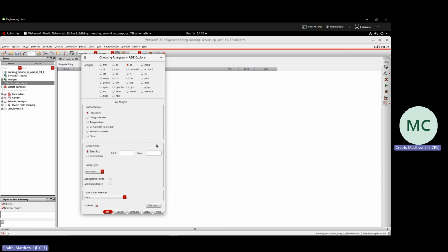So the gain bandwidth for a single pole system, which our op amp is, should be about the same as the unity gain frequency. So we expect it to be about 10 megahertz. So I'm just going to go 1 decade beyond that to 100 megahertz. So we can put 100, capital M here.